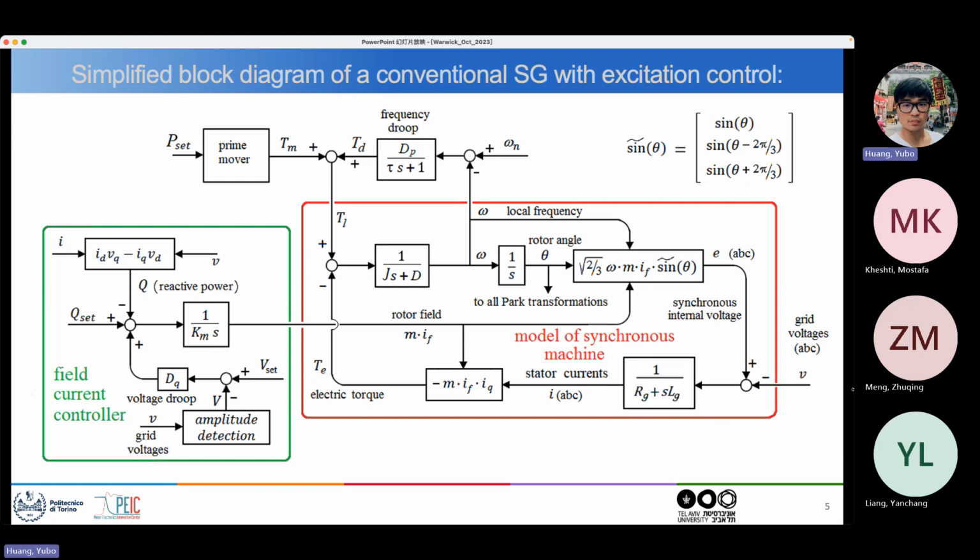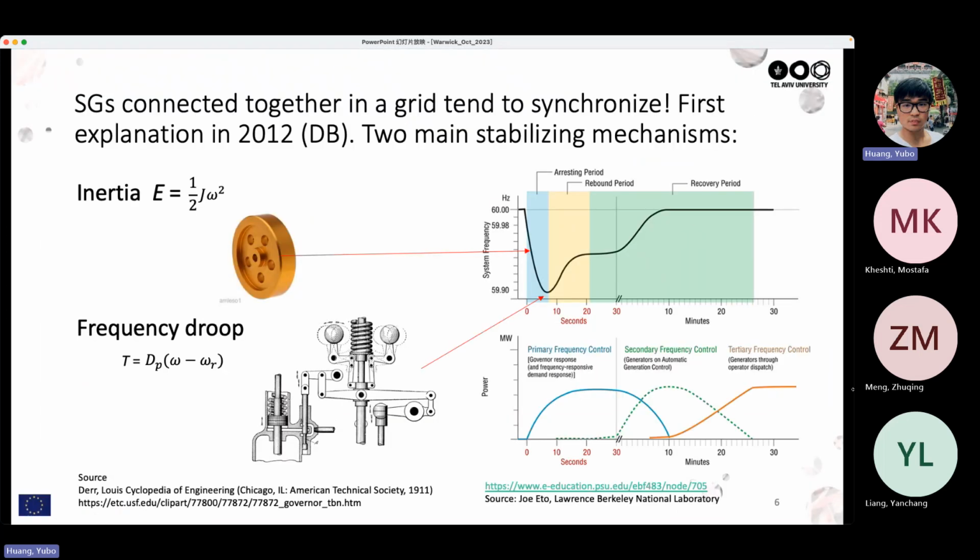And now when inverters started to be used in the power system, then inverters had none of these stabilizing effects. They did not have inertia and they did not have a frequency droop. Then slowly these things started to get into inverters, and then people started to distinguish between grid-forming inverters and grid-following inverters, for the reason that if you replace